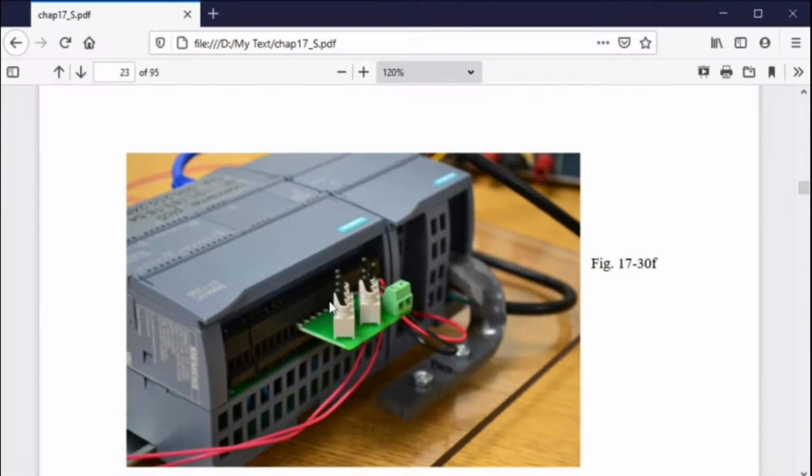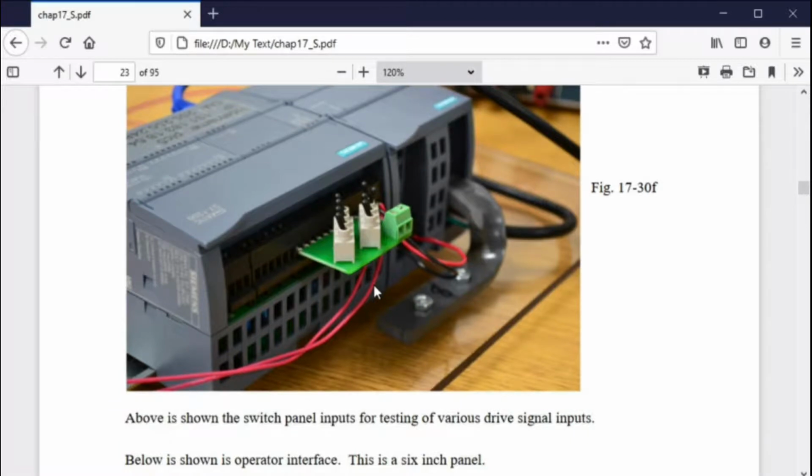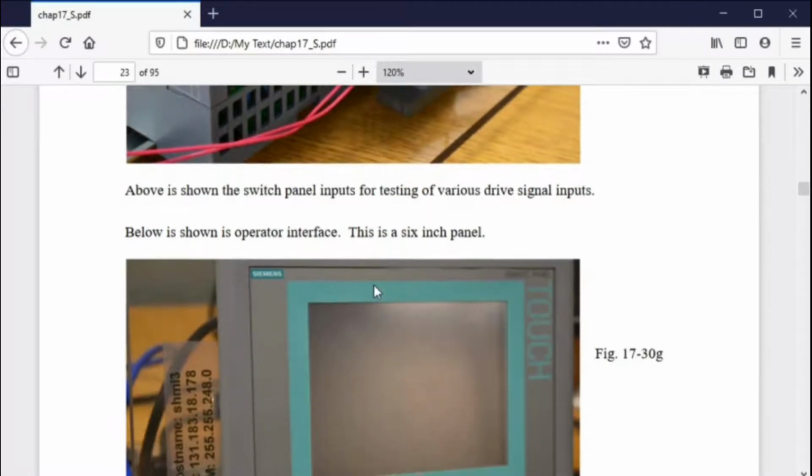So here would be the PLC, and these switches are referred to in the program. And we leave those on because they're very handy ways of starting and initializing our system. And instead of having it on an HMI panel, you can just flip these switches and you can try your system out. The goal of each of these systems is to get something to run. If you can get the axis to turn, then the rest of it, while it's not trivial, isn't that hard. But getting it to run is a key part in all these.